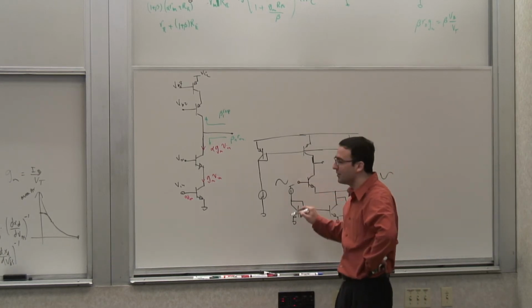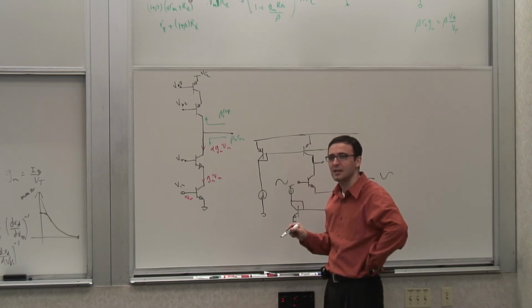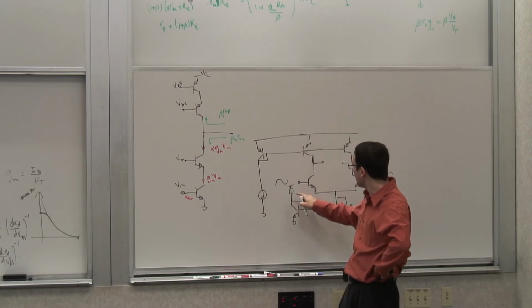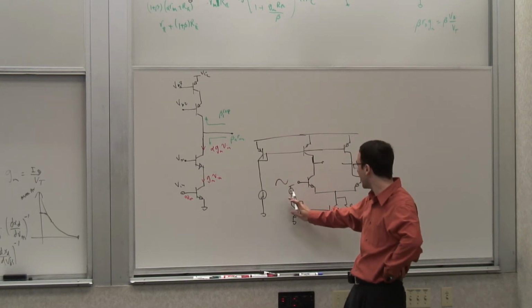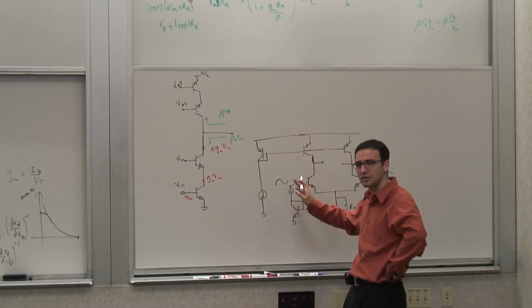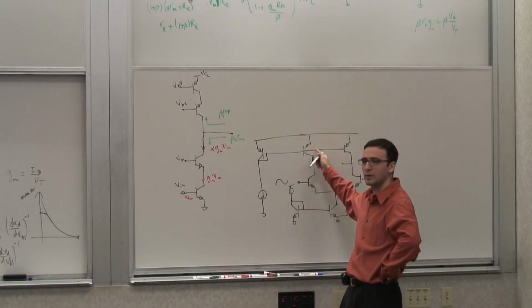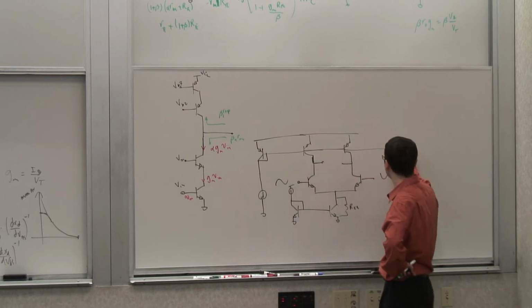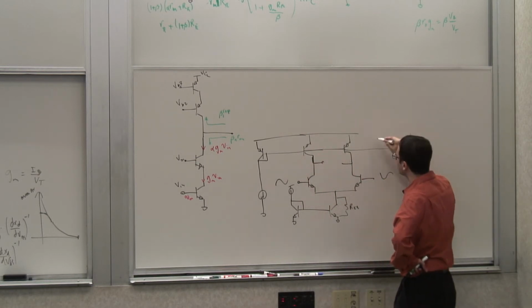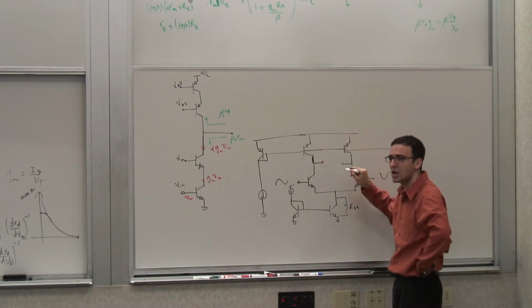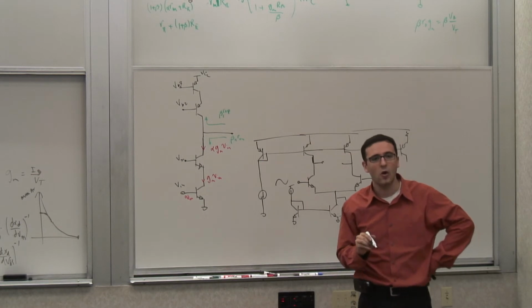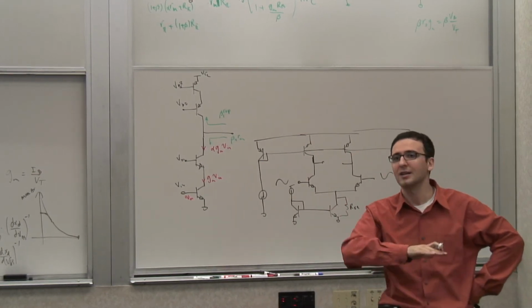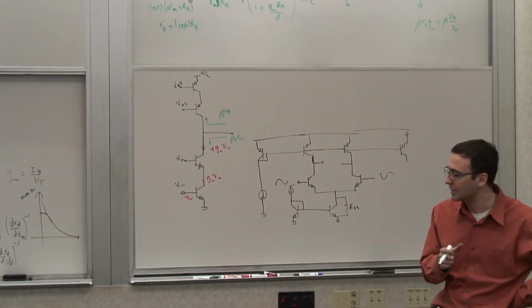So, one thing that we did in this case, we assumed that we have a reference branch, and if you had a reference branch, you could actually replicate it many times using this current mirror right here, like this one, where you could replicate it twice, and could replicate it more often, and I could get different ratios by adjusting the ratio of these guys, or I could make it smaller by putting a resistor here, like a Widlar current source, or I could even make the current mirrors cascode, and you look at all of those.